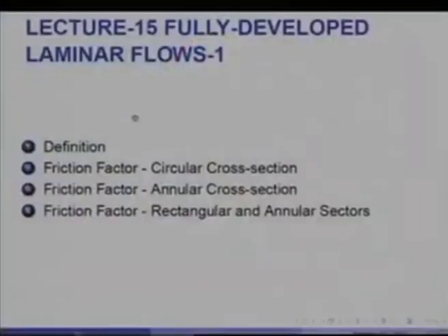Today we will look at fully developed laminar flow in a duct. We will begin with definition, calculate friction factor for a simple circular cross section duct as well as annular cross section duct, and then somewhat more complex ducts like rectangular duct or an annular sector duct.